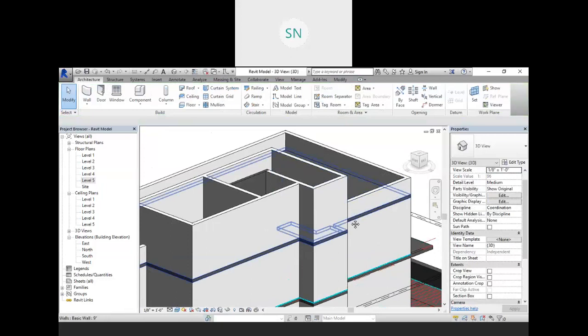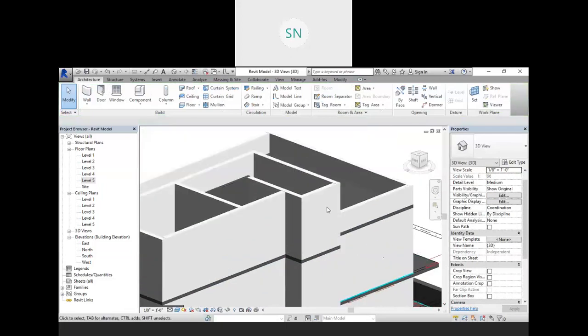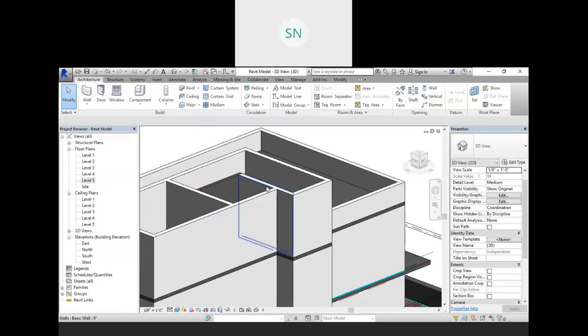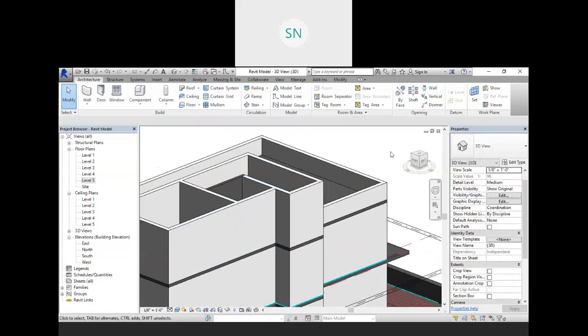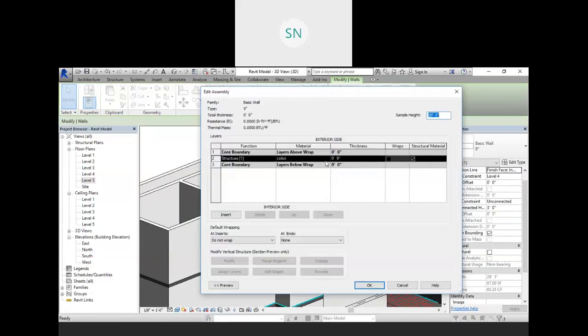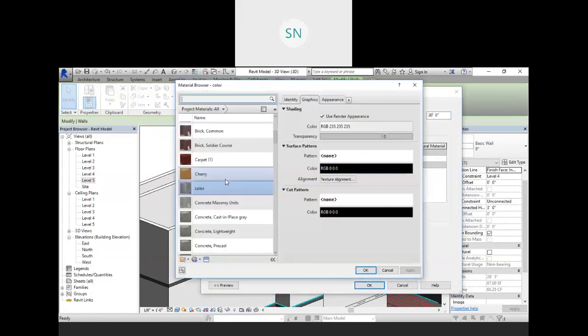And for example, I just want to apply some different color to this face only. So what we can do is go with the modifiers, but before you go there you have to create that material. And you know how to create a material. To create a material you have to choose any object, then go to edit and go to the materials. From here you can create a material with the duplicate option.